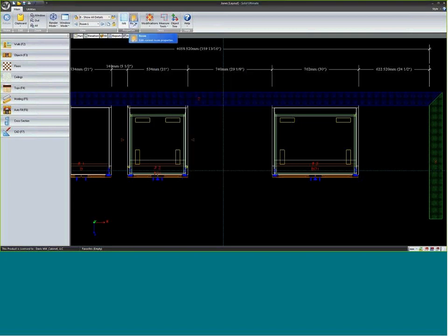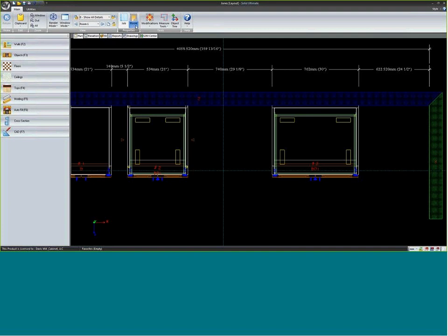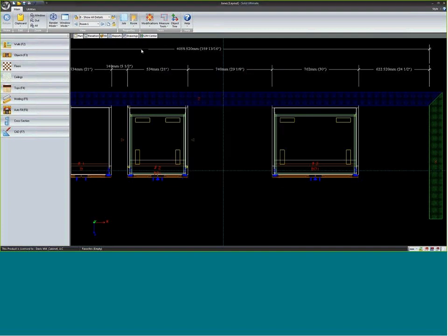Now, the room button can be a little bit confusing. If you'll notice when I hover my mouse over it, different halves of this button light up. The bottom half we briefly mentioned yesterday. I can click on that and go to my catalog and re-enter specifications for this room. Right? It's on the room button. Specifications I enter here will affect this room.